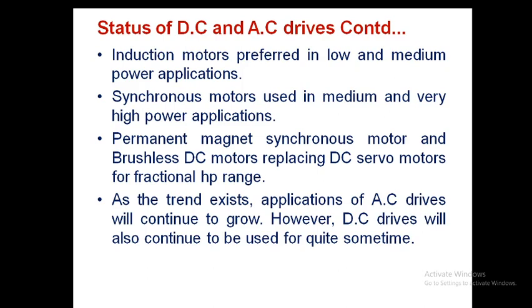Really, we use a DC series motor in traction, with thyristor circuits. That kind of drive we are using in traction nowadays. In a few traction applications, in a few locomotives, we are now using induction drives also, that is AC drives.